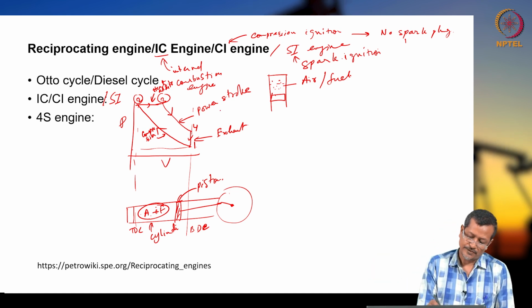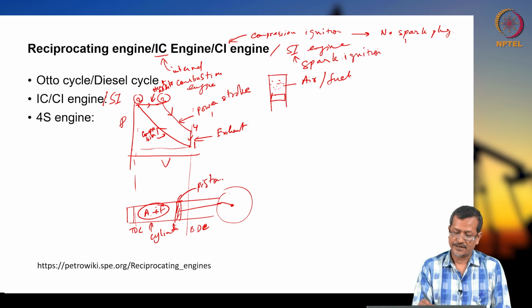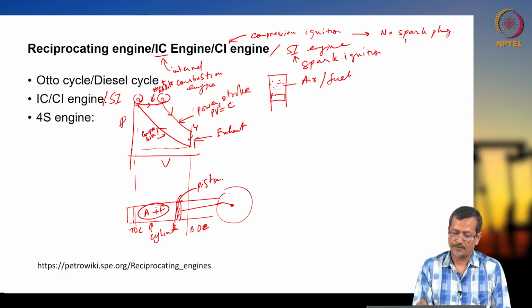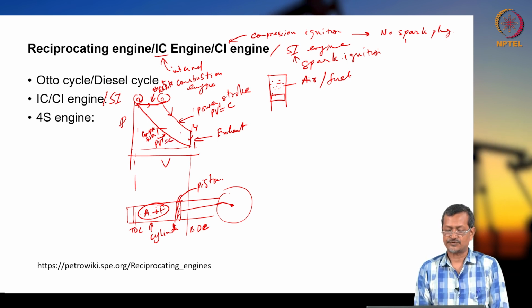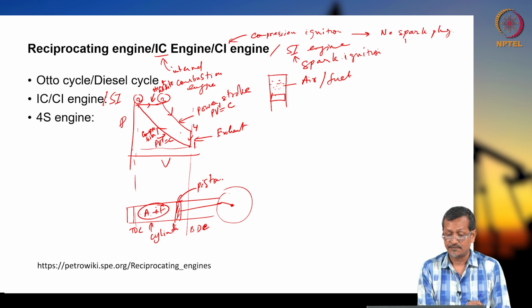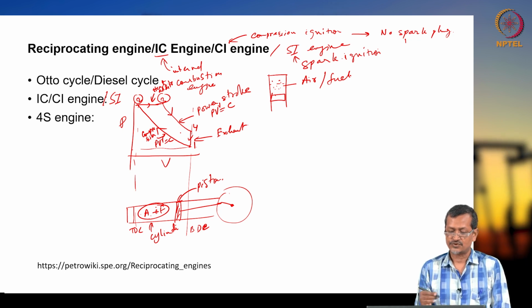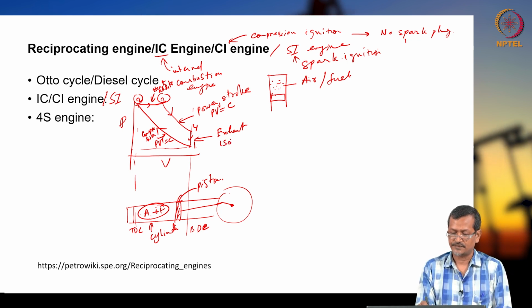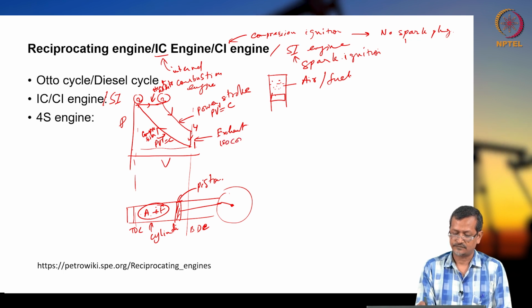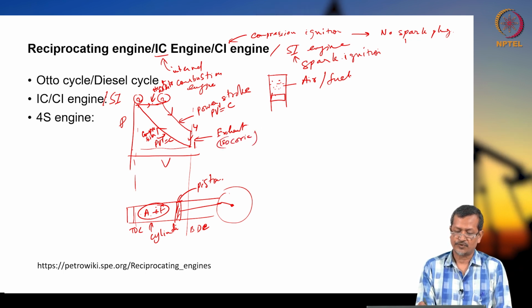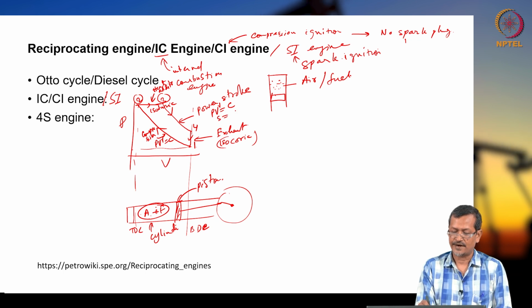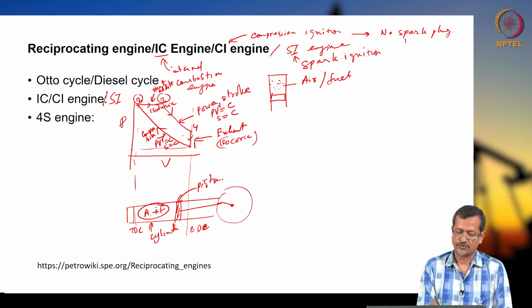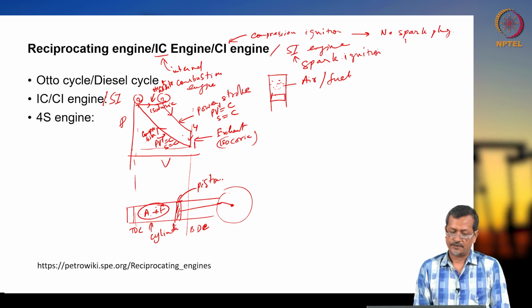Okay. So, that is called the power stroke, and in both cases PV^gamma equals constant. We are assuming an adiabatic process, since this is a very fast process. For exhaust, we are assuming an isochoric process, which means an isovolume process, and the heat addition process is isobaric. Okay, PV^gamma equals constant, or entropy equals constant, entropy is also constant. Okay. Now,